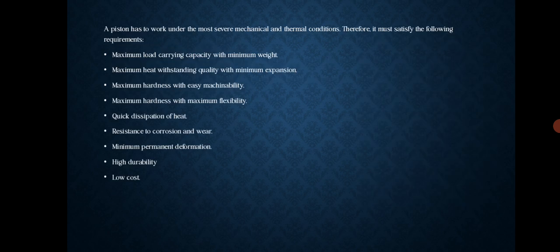Piston has to work under the most severe mechanical and thermal conditions. Therefore, it must satisfy the following requirements: maximum load carrying capacity with minimum weight, maximum heat standing quality with minimum expansion, maximum hardness with easy machinability, maximum hardness with maximum flexibility, quick dissipation of heat, resistance to corrosion and wear, minimum permanent deformation, high durability, low cost.